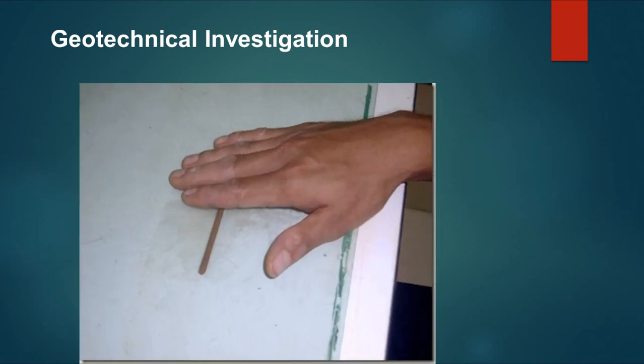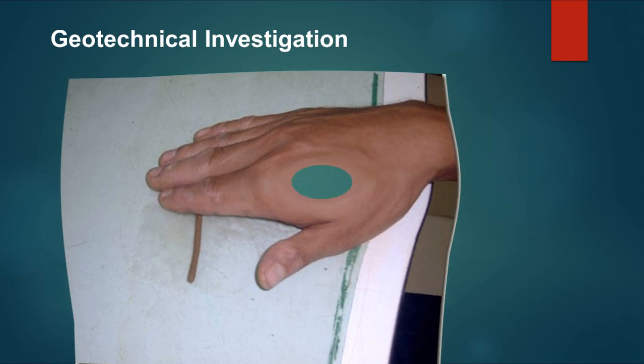The plastic limit is determined by rolling a soil sample into a thread of 3.2 mm diameter. The water content will be reduced until the soil thread crumbles and can't be rolled. At this point, the water content is the plastic limit.